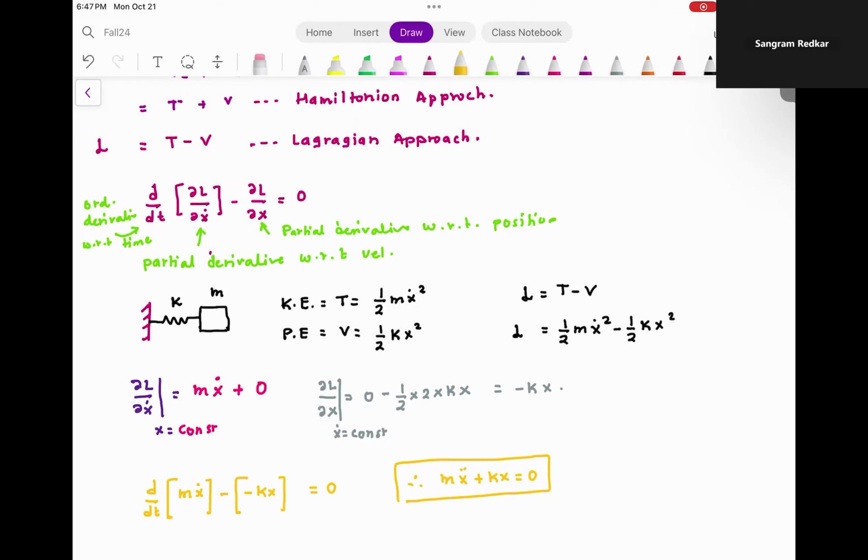If you look at this, I have not drawn a free body diagram. I have not even drawn the coordinate system. I don't care because my potential energy is a positive scalar function. My kinetic energy is a positive scalar function. I just found out the kinetic energy and potential energy for this mass, and boom, I get this differential equation which is given over there. Everyone understood this?